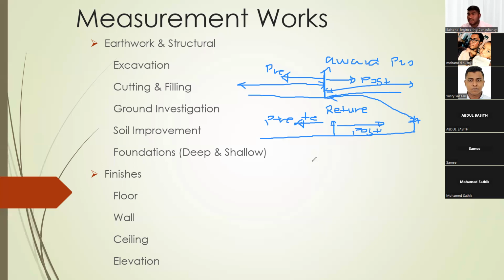So the client will tell, compare the contractor price, compare the return you get from the contractors with your pre-tender estimate. So for example, for a cubic meter of concrete, as an engineer, you estimate 1,500 per cubic meter, but the contractor is submitting 3,000. So the client will go one by one and look at it and ask why your price is low, the contractor price is more, something like that. So that is what they ask of the estimation from the engineer. One is to focus the project budget. The other one is to see the performance of the engineer, how he's working.